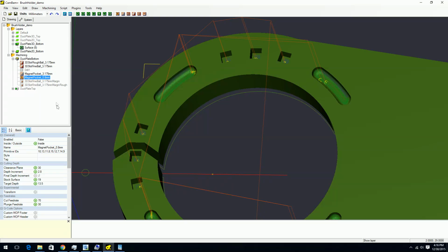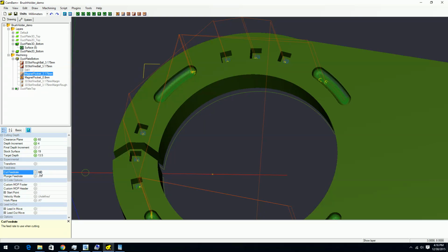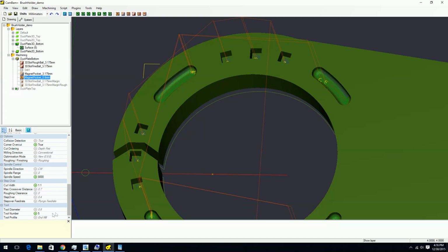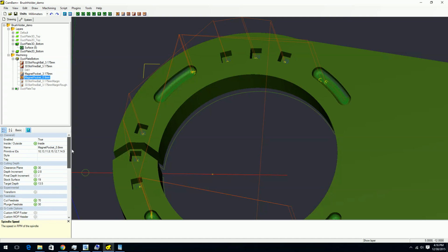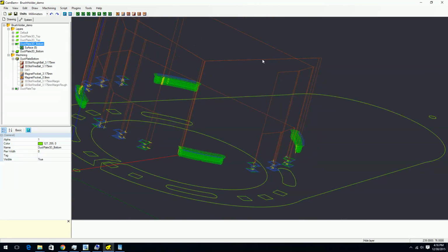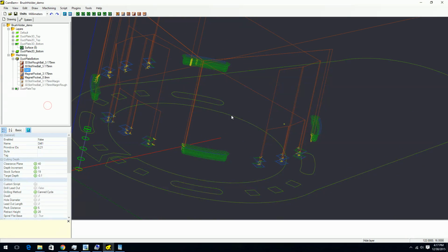To do that, I use a different machining operation with a much finer bit, 0.8mm, and I will go very slowly with this bit because it is so fine that if I went any faster, I would break the bit in the machine. So here you see a very fine bit, 0.8mm. And we'll go in 2 steps. So here you see the machine operation. The outer 2 lines are for the 0.8mm bit.